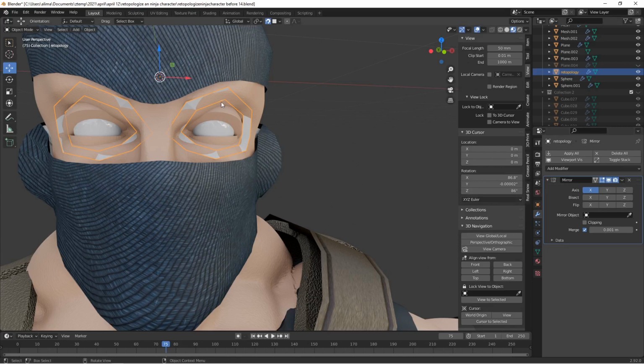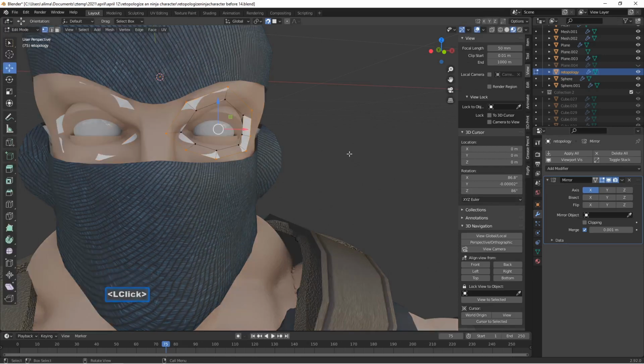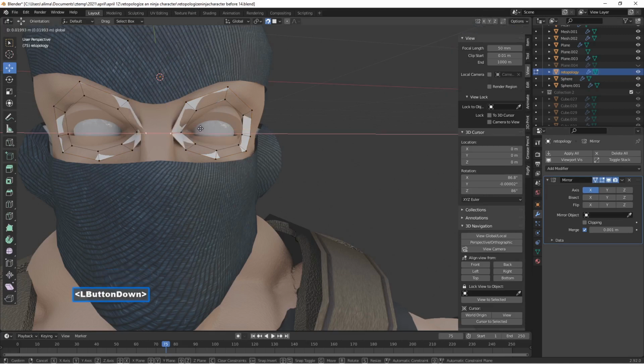So with this done, what we're going to do is go back to the upper left, go back to edit mode. I'm going to go to this mirror modifier. See, this looks like a triangle. When I select this, this will make this mirrored geometry look like this geometry. So that makes it easier for me to work. I'm going to select here, pull this back some like that.